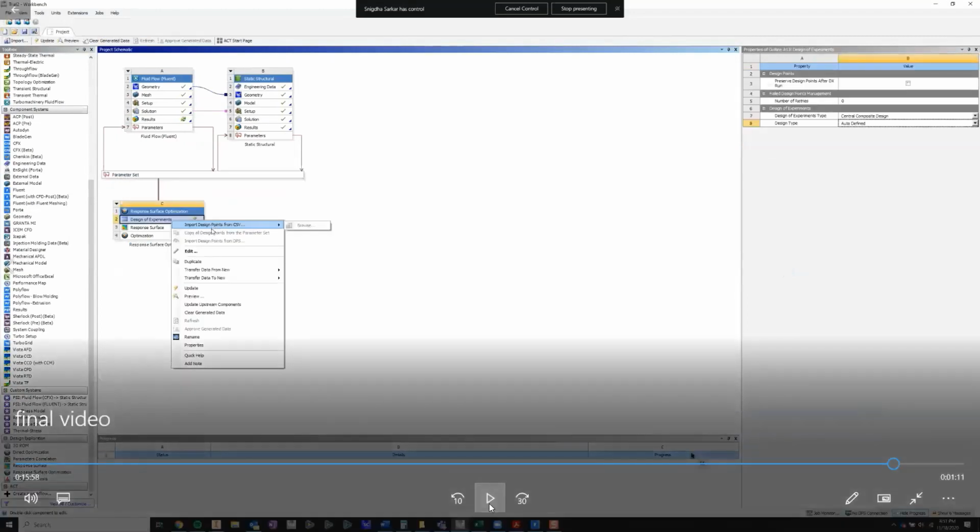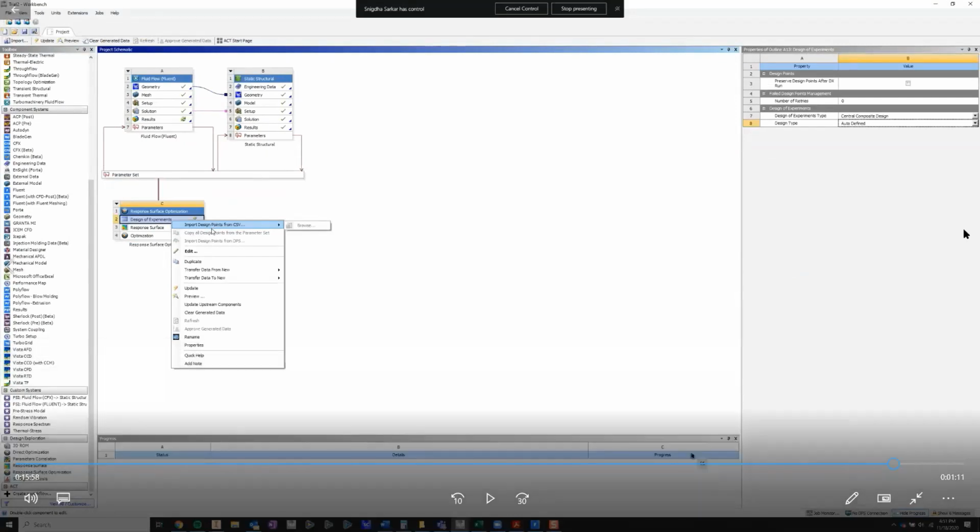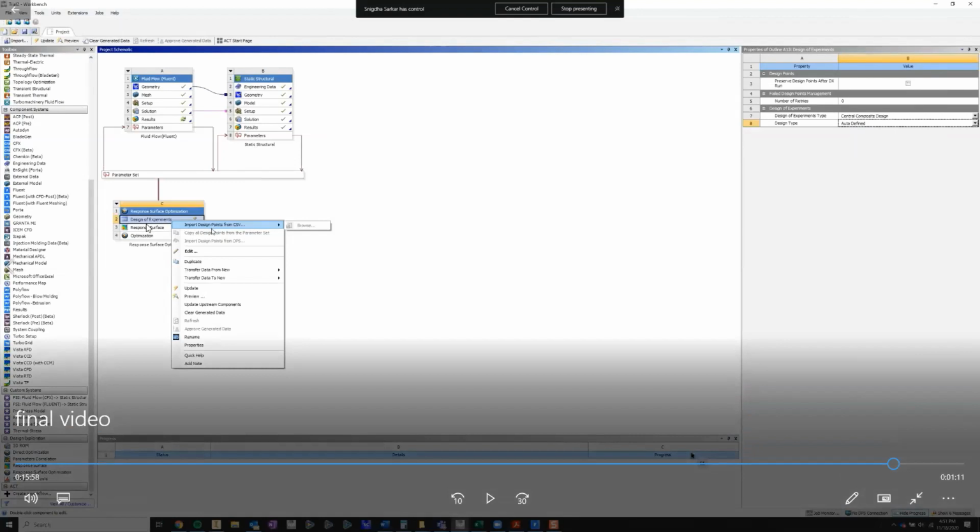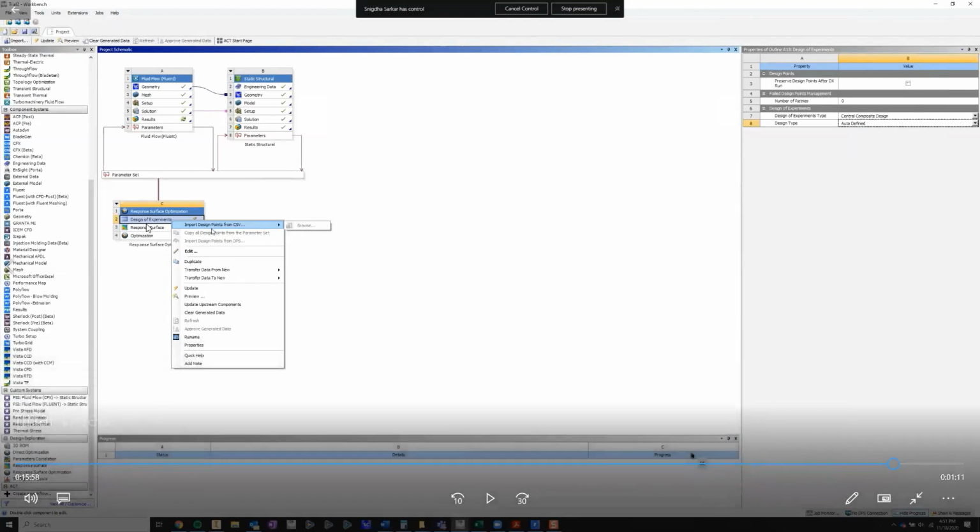Now, I just want to pause the video over here and talk about something very important. If you're just doing a parametric study, if you don't want to do a design exploration, if you're simply doing a what-if study wherein you're changing one parameter and seeing how it impacts your output parameter, then you don't even need to do the design of experiments. You could just simply do that in Workbench. And depending on your hardware resources, you should be able to get your answers accordingly, right?